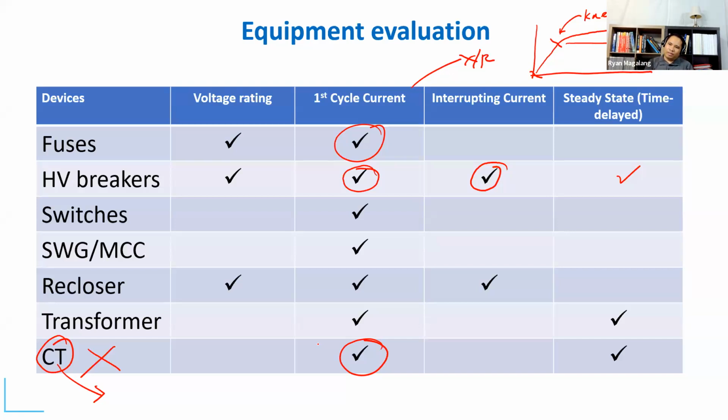But how much is the capacity of that? You could probably approximate. The thing with solar, the panel itself, the fault current that it generates is almost the same as your rated current. It's not like your motor, where the fault contribution is like 6 times your full load.